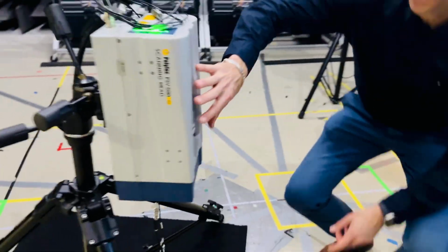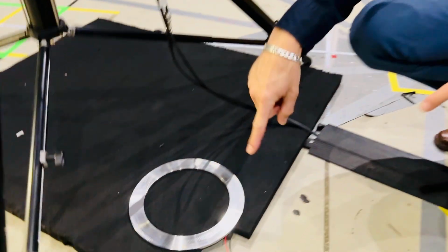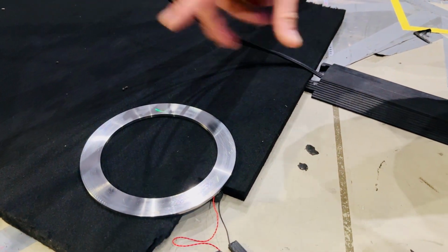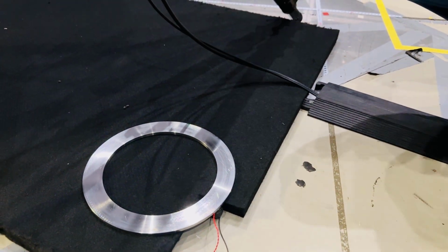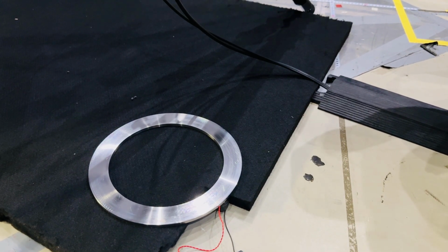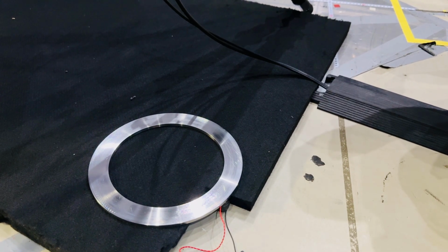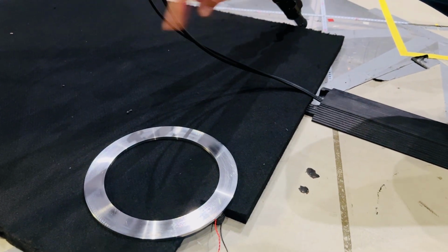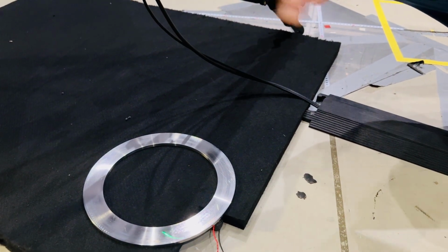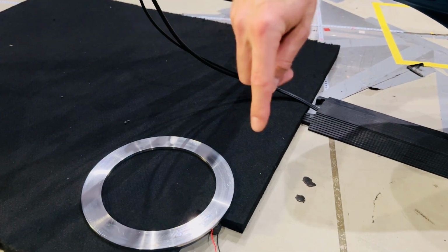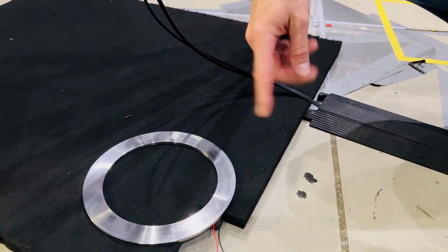This is my scanning laser vibrometer, and I'm using an external signal generator to drive the X and Y mirrors within the scanning vibrometer such that the laser beam is scanned around in a nominally circular profile around this axisymmetric steel ring, which is an example structure for which we understand very nicely the expected vibration behavior. We're essentially modulating the sine and the cosine to produce a varying amplitude circular scan with different frequencies for the scanning and the modulation of the radius of the circle.